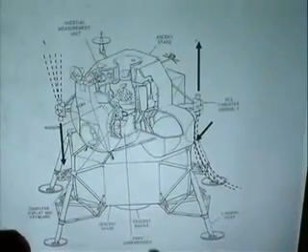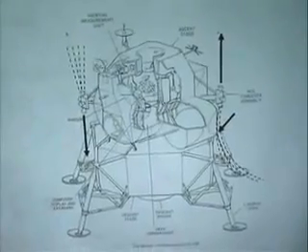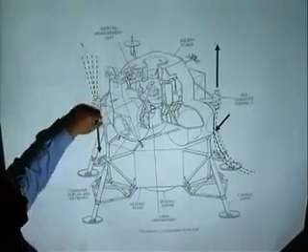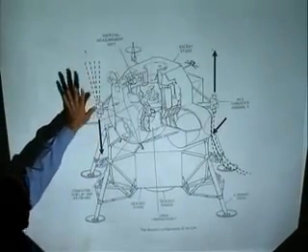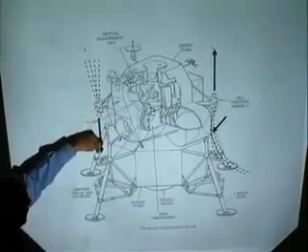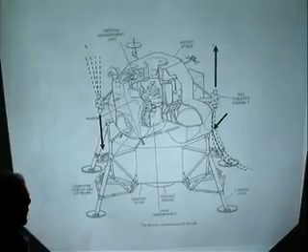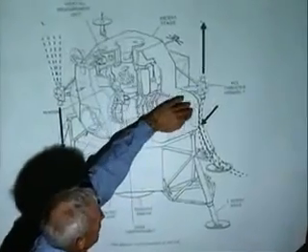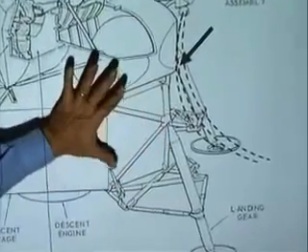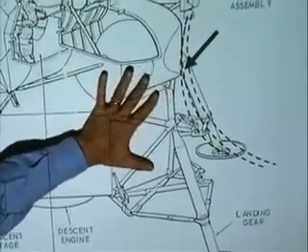Well, if this is docked to the lunar module, you had to start worrying about some other things. First of all, you couldn't be exhausting into the astronauts' faces in the command module. That wasn't any good. And when you exhausted down, there were these splash guards here that kept the exhaust from ripping up the gold foil that was providing thermal protection on this stage here.